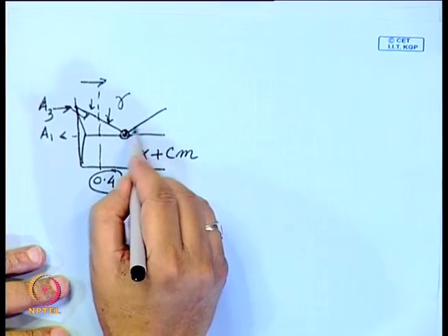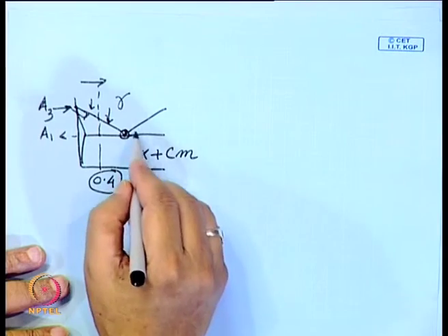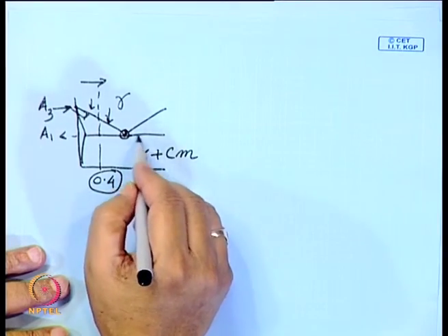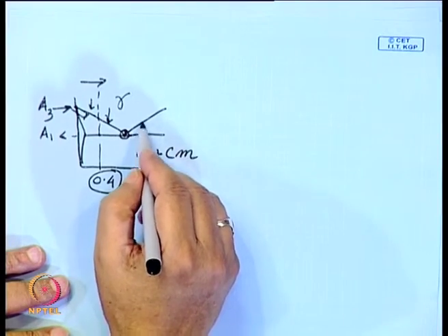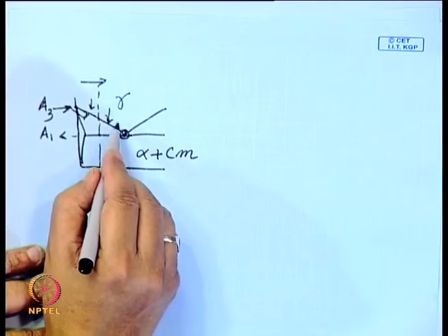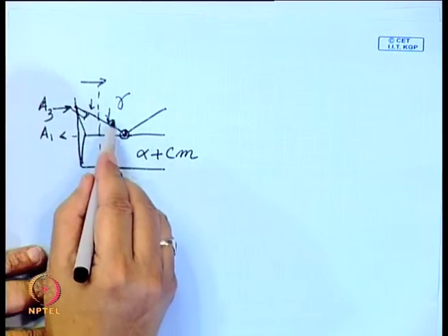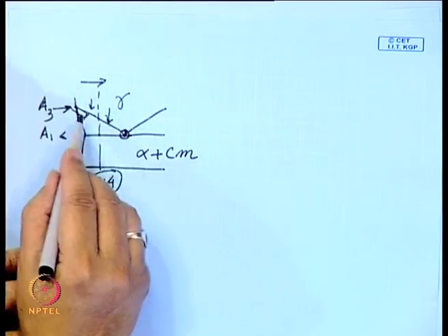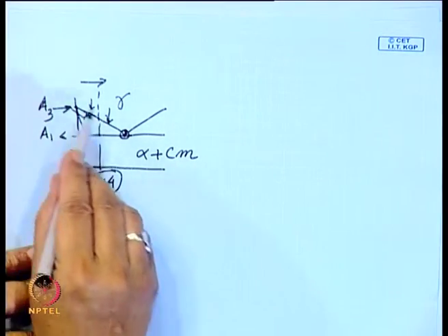But this part is not important; except for tool steels, we rarely use it application wise. Bulk of the applications will be in this regime, and therefore for most cases we can say that carbon is an austenite stabilizer within this limited range.